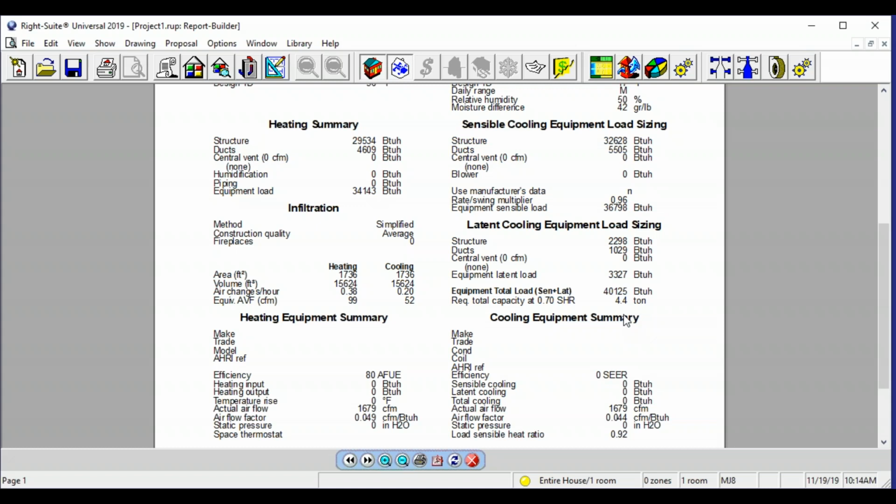Some of the 3.5 ton units out there, I mean, sounds crazy, but I've seen really high efficiency 3-ton units that are only pushing out 39.5. So if you're looking at your total amount, you're not going to meet your total amount at 39.5. At that point, you might have to jump to the 4. So you always got to look at the unit you're doing and what the unit is capable of. And if you live in an area that has latent, I would always 100% make sure your latent is taken care of for latent and moisture removal inside the home. If you don't do that, you're going to be in deep trouble. That's a major, major area.